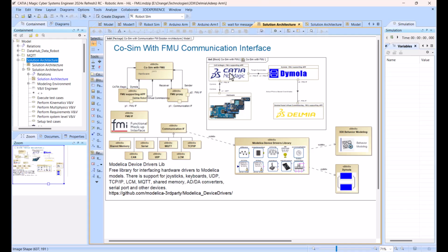And whatnot, it's up to us. The core thing is that this standard is enabling communication. As you can see here in this environment, we have FMU supporting apps, like internal and external, like Simulink supports FMU, and then those proxies, like server, client, site, generated and added to those apps to communicate through that interface.